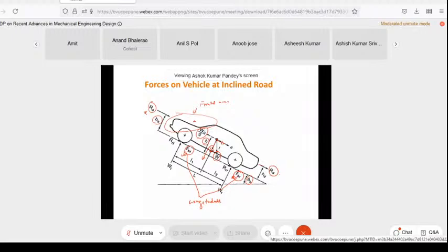Now there may be rolling forces, which may be a little different, and that also needs to be considered. After you consider all the tire forces, dynamic forces, the trolley force that you are having over here, and then weight, you are ready to write the equation of motion along and vertical direction, right? And also you can write the moment about one of the wheels. The one motive that we have is to first find out the normal loads at the front and the rear wheels, and after that only you can find this and this, right?